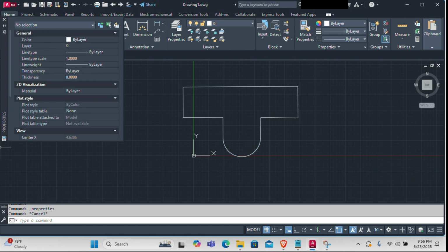Now in electrical drawing, you can use polyline when drawing paths that curve and continue. You want to fill areas like busbars or grounding zones, or you need to adjust all segments at once. Always check whether your shape is better as a single object or separate lines, and use it according to your intuition. So that's a wrap for day 7.